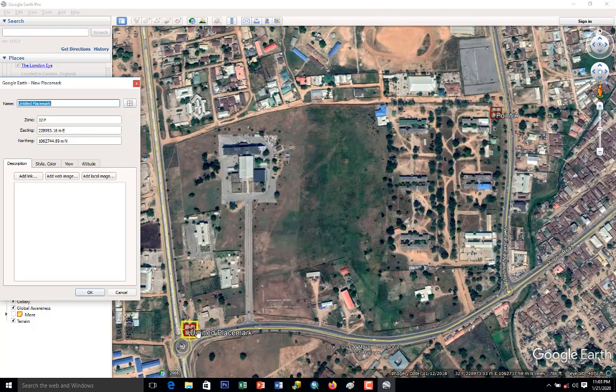Because we are going to save the image of this, by the time you georeference and you want to trace, it will shrink to a particular side. If you pick this point and this point diagonally, it's going to stretch the image perfectly, because it uses this as the starting point and stretches it to this extent. It's just like holding the edge of a line from the left corner side and the upper right hand side.